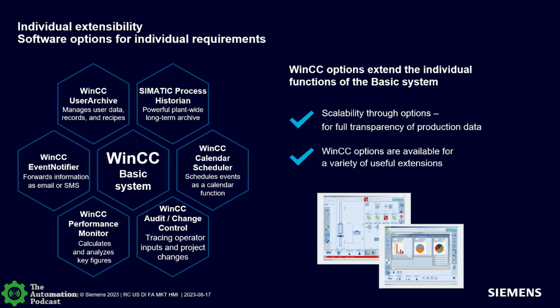WinCC user archives, if you need to do recipe management or data management, because you're taking readings from the field and you need to store them in your WinCC database, you can use WinCC user archives for that. And that gives you the expansion to, hey, let me create recipes so I know what cookies I'm making today, or I've got batch testing information I need to pull back into it.